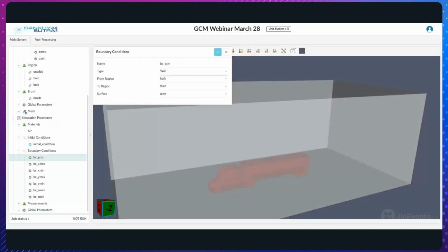is a static pressure outlet boundary condition, the inlet BC, which is a constant velocity inlet boundary condition. Symmetry is the symmetry boundary condition, and wall is the no-slip boundary condition. We also offer periodic and the moving wall BC for your rotating or oscillatory needs. So I'm just going to click on OK, apply.